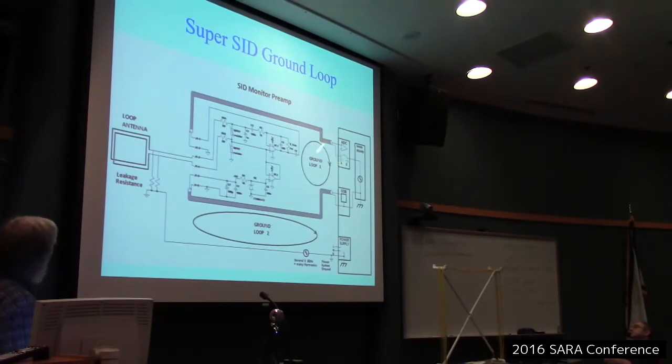So it goes around, and you turn up with some of your switching power supply noise from the computer showing up there. In the case of the antenna circuit, if there's any leakage to earth ground at the antenna at all, you could get small currents, and this over a substantial difference in, like, a ground rod or grounded point out here, which isn't tied with copper back to there. You can see some pretty substantial voltages there, enough to really interfere with stuff.